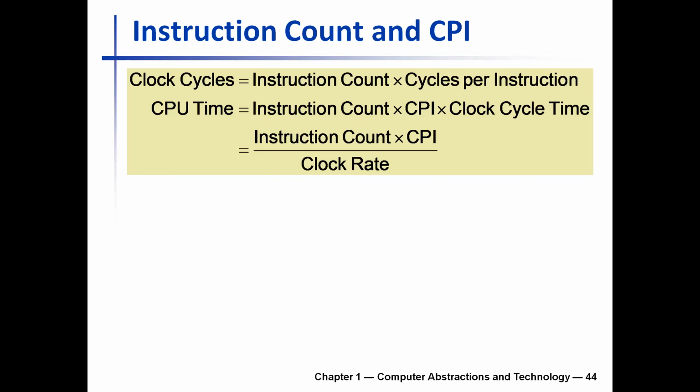In multi-cycle processors, this is different. The hardware is designed in such a way that an instruction takes multiple clock cycles. The decoding part will take a clock cycle. The reading of the register values will take another clock cycle. Then doing the actual operation, like adding or multiplying, will take another clock cycle.